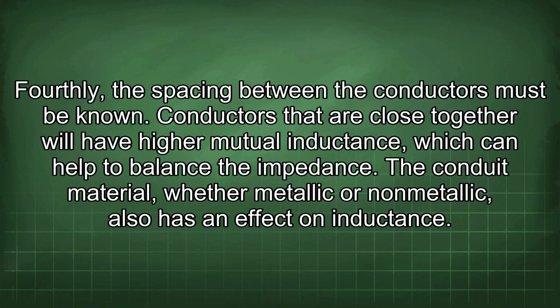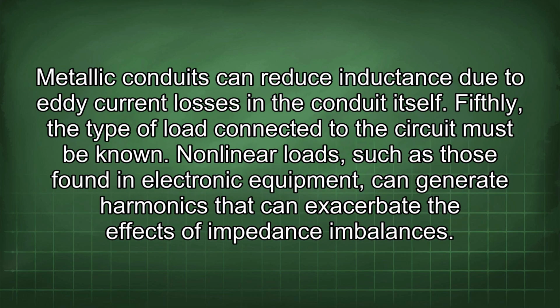The conduit material, whether metallic or non-metallic, also has an effect on inductance. Metallic conduits can reduce inductance due to eddy current losses in the conduit itself. Fifthly, the type of load connected to the circuit must be known. Nonlinear loads, such as those found in electronic equipment, can generate harmonics that can exacerbate the effects of impedance imbalances.